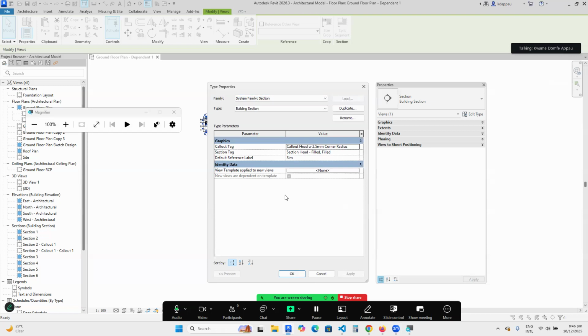Okay. When you have a wall and you want to get a different wall type, you have to select the wall, edit the type, and it will bring you to this type properties palette. And there are so many things about the wall that you can edit. But before then, you can create different wall types. If you select a duct, you can create different duct types. Window, different window types. Column, different column types.